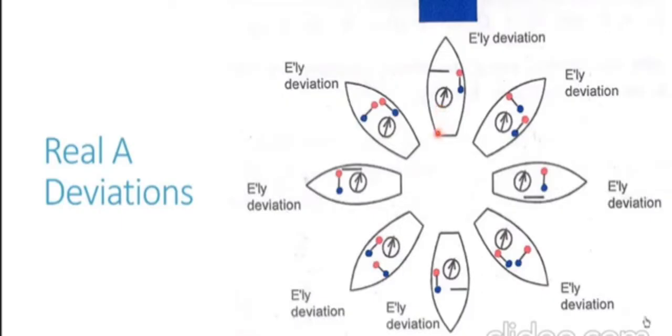So let's concentrate our attention on the ship on the northerly heading. The ship is on a north heading. You can follow the laser pointer. This is the diagram which we are going to understand in detail. Now the ship is on a northerly heading. We have these 2 soft iron structures. One an athwart ship beam which is only present on the port side of the compass, and we have a fore and aft longitudinal which is present on the starboard side only forward of the compass. It is not present aft of the compass. So we have combination number 1 which we saw in the previous slide, an unsymmetrical pair of horizontal soft iron structures. You see this big blue color rectangle on top.